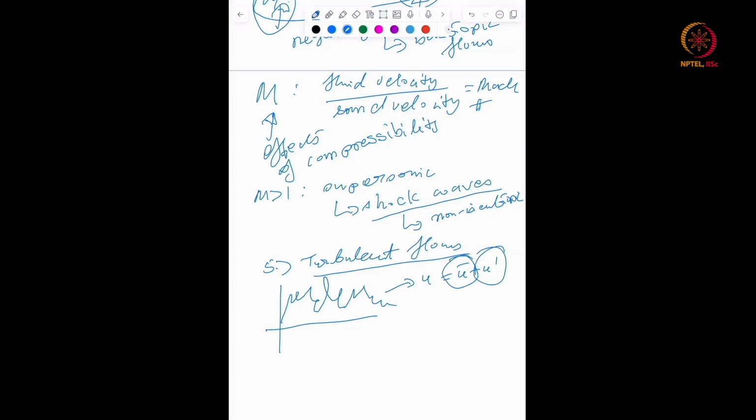To put it very crudely, the velocity, pressure, vorticity, all the variables, U, P, omega, even temperature if you have one, will vary randomly in space and time. The randomness requires a statistical description. For pressure also there will be a mean and a fluctuating component.